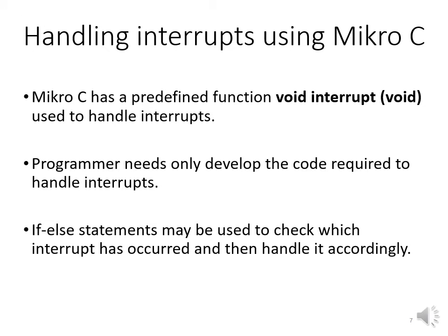MikroC has a predefined function for the purpose of handling interrupts. The programmer only needs to develop the code that would be required to handle the interrupts. This code must be inserted as the body of the predefined interrupt function. Since the function is used to handle interrupts from all the possible sources, an if-else construct may be used to check which interrupt has occurred and then handle it accordingly.